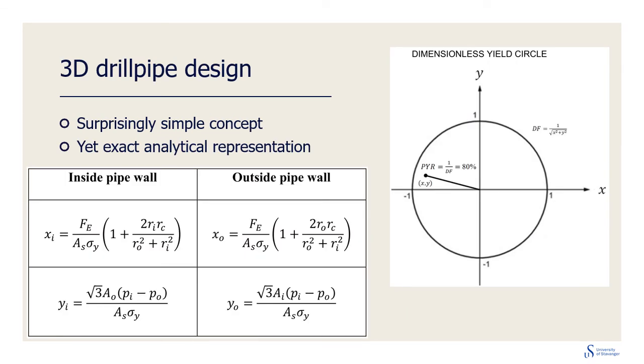Real axial force and zero stress datum produces a triaxial ellipse, while effective force and neutral axial stress datum produces a triaxial circle. In this paper, we use the latter due to simplicity and agreement with buckling stability. For drill pipe and snubbing workstring, the diameter-to-thickness ratio is low, and collapse failure is modeled as a yield failure. We can therefore make the circle of plasticity dimensionless as shown.